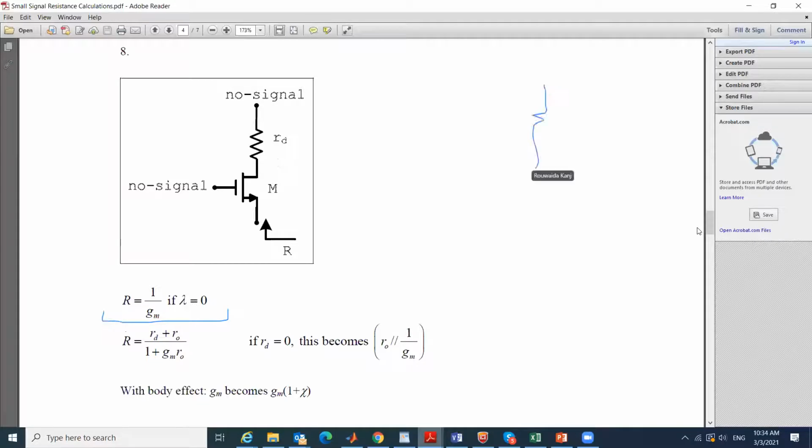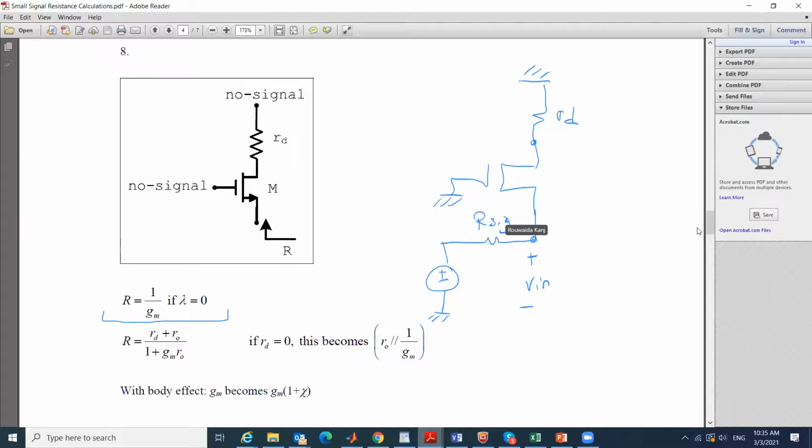If I give you now a common gate amplifier, pardon me, with some V sig and R sig, and I tell you that this transistor has some RD or R load at this node, and this is our Vn because Vn is at the end of R sig, and I ask what the input resistance is, automatically you will take this rule: if I have RO, I will be relying on RO, RD, and gm. If not, it is 1 over gm. So Rn is 1 over gm, which is what we just proved in the small signal analysis of this circuit.